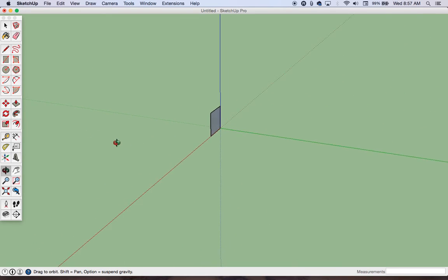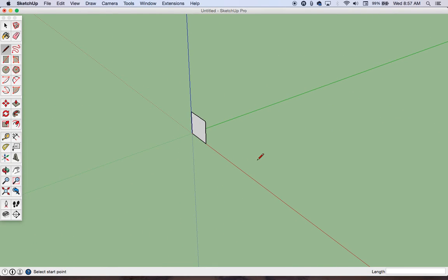So when you're going to create three-dimensional objects, this next tool, which takes us from the 2D realm into 3D, is the push-pull tool, probably your third most used tool if I had to think of one off the top of my head. So I'm going to click on that surface using the push-pull tool. Also happens to be the letter P in your keyboard shortcuts. If you know the name of the tool, it helps with the keyboard shortcut here.